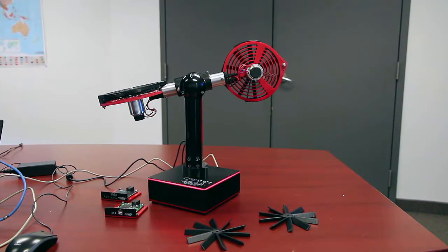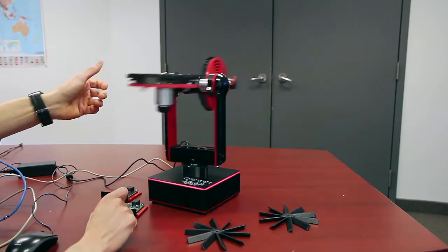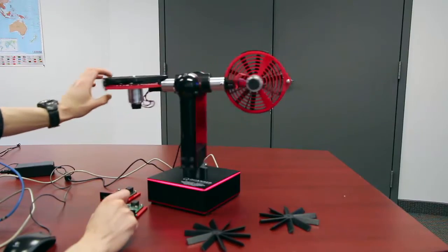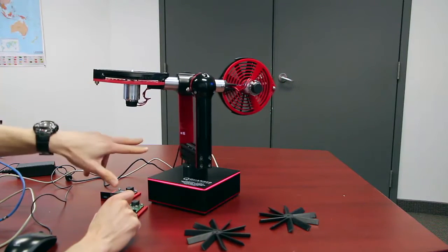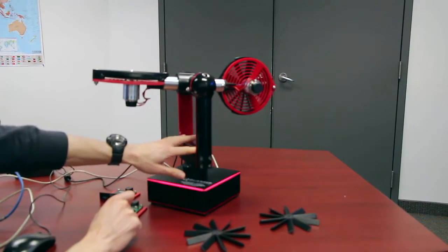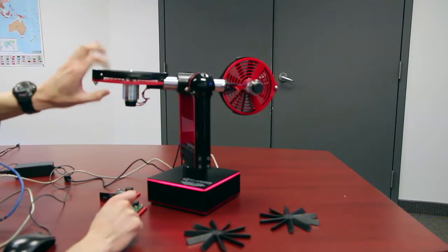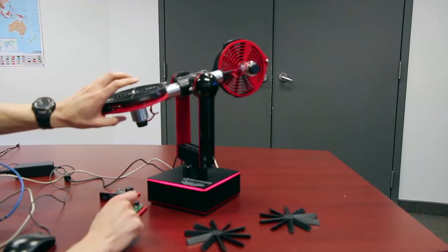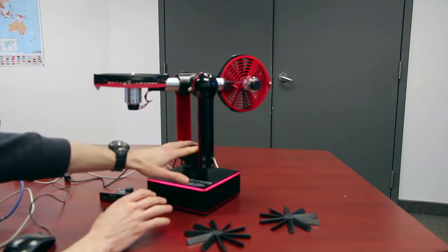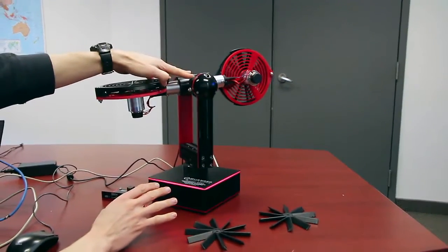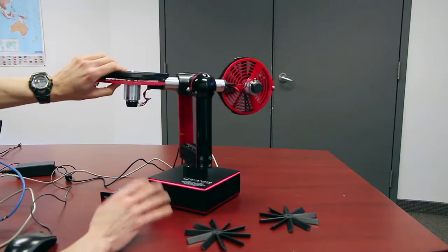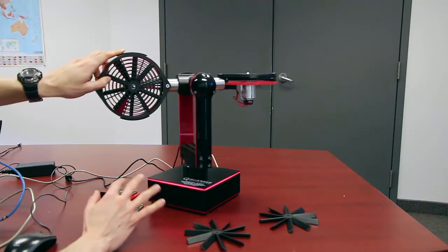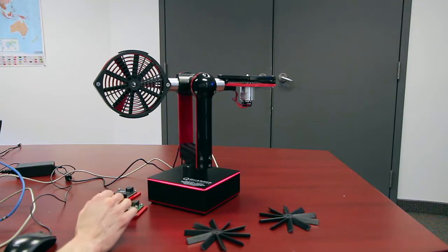Now let's talk about different configurations you can do. As you can see here, the yaw has a slipper design that allows you to move it continuously 360 degrees. But you can choose to lock the yaw if you want using the Allen key. So if you want to conduct experiments only in the 1 DOF configuration, 1 degree of freedom pitch, you can lock the axis and just do that. Similarly, you can lock the pitch. You can also adjust the angles of each rotor. We'll go through 3 different configurations today, so you can have an idea of how you can change between different configurations.